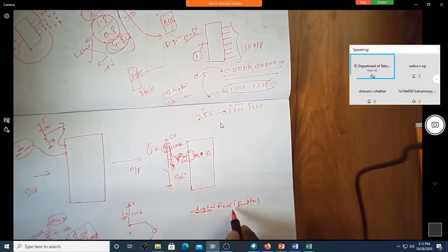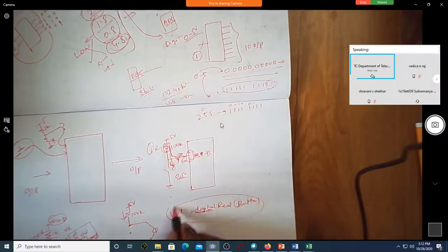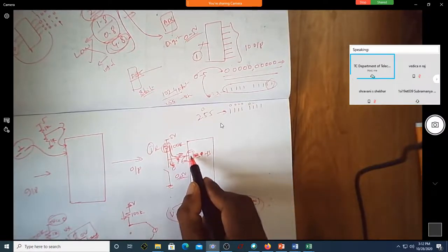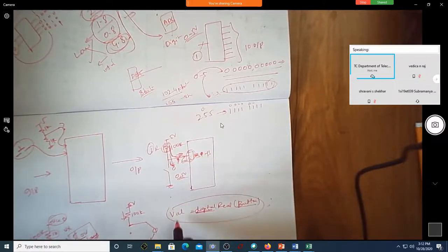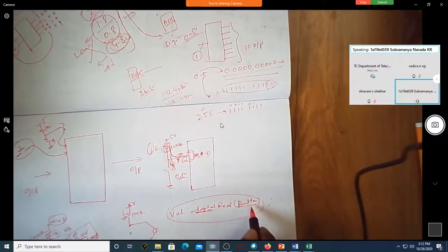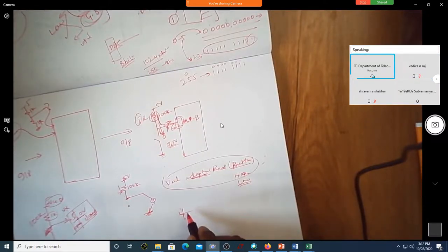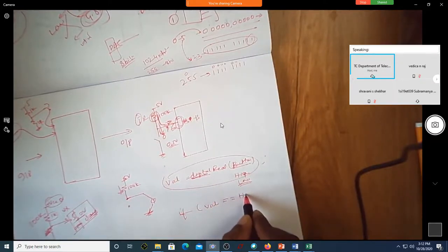So this digital read, whatever value that you read, has to be assigned to some variable which we name as val. After execution of this statement, the value of the button, that is the value at this pin number, will be assigned to val. What are the possible values of this digital read? It can be either 0 or 1, high or low. That's why in the next expression you will just find out if val is double equals high, you do something.